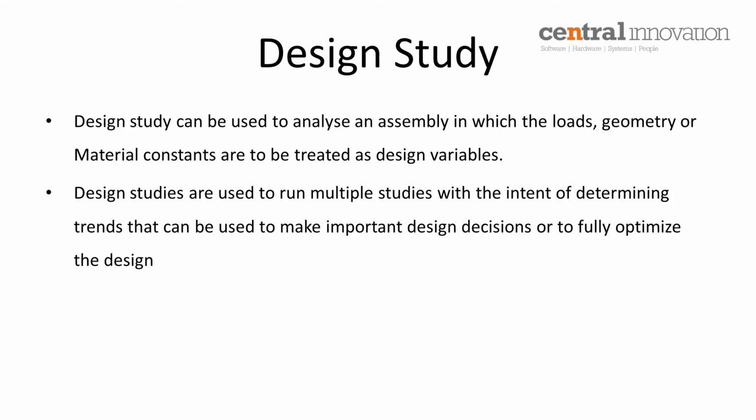Your variables can be your load, your geometry dimension, or your material property. Here is a simple example. I have created a design, and I want to test which material is the best material to use. I'm worried about the design safety or factor of safety. I want to maintain the design safety within the limit. At the same time, I want to maintain the stress within a certain limit and the displacement within a certain limit. I know the design limit values for the stress, displacement and safety factor. So those are my constraints.